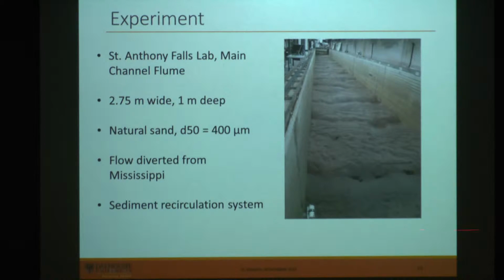And then another nice feature of this flume is the recirc system. Just behind where this photo is taken, there's a gap in the floor of the flume where the sediment gets collected and then pumped back up to the top of the flume. So you can run the flume indefinitely and look at equilibrium bed states and things of that nature.